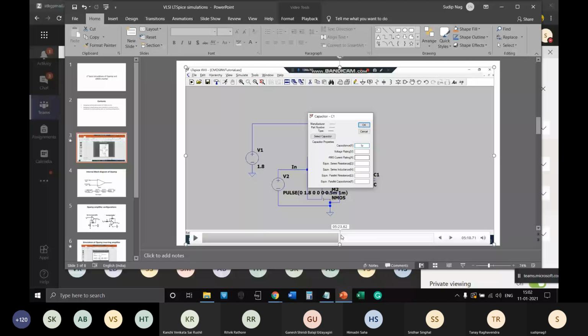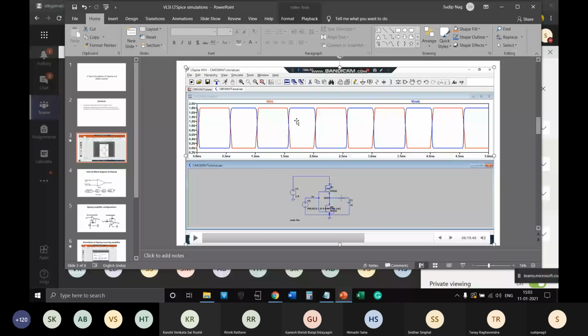You have to charge and discharge a capacitor, and that is why you get rounded edges. So if you look at this waveform carefully, red is the input, right? Red is relatively sharp, although it has some rise and fall time, but it is relatively sharp at the edges, at the corners. But the blue one is relatively curvy. That happens because of the capacitor.